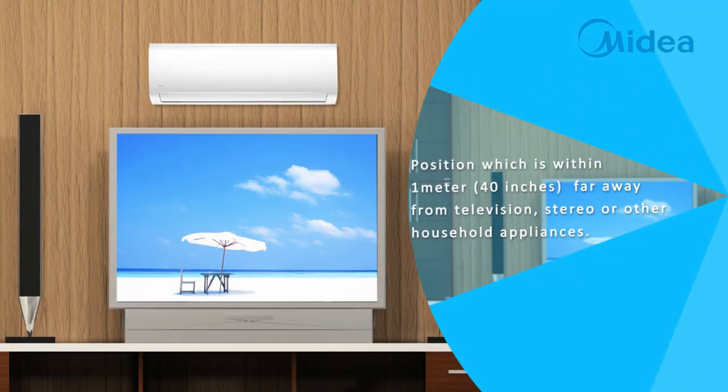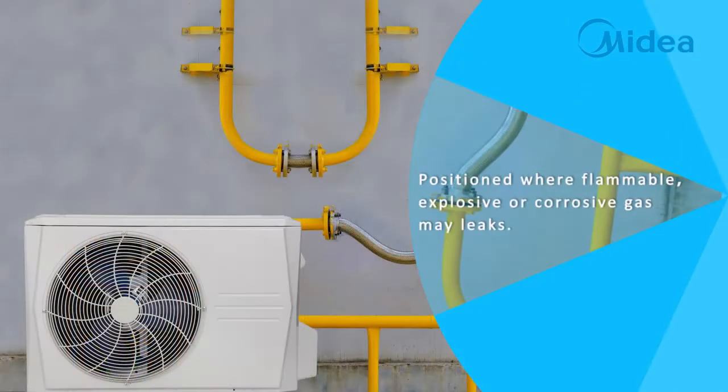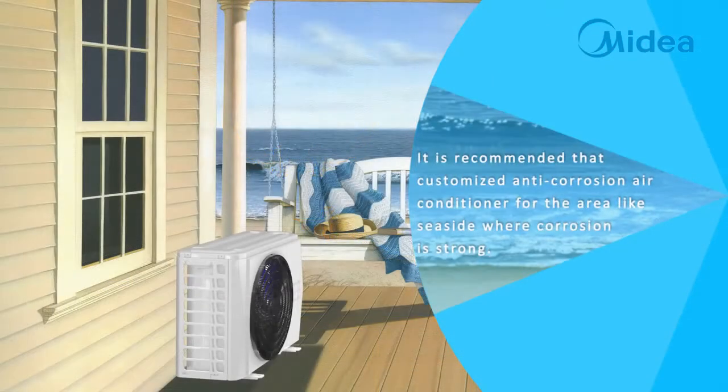Position which is within 1 meter, 40 inches, from television, stereo, or other household appliances. Ventilation is poor and there are obstacles around, which may affect airflow. Position where flammable, explosive or corrosive gas may leak. It is recommended to use a customized anti-corrosion air conditioner for areas like the seaside where corrosion is strong.